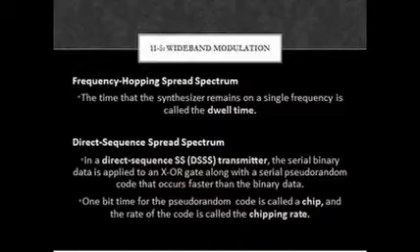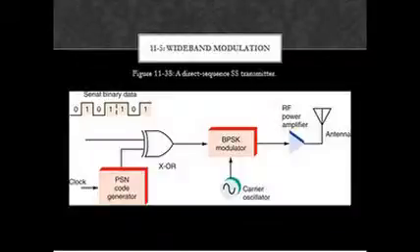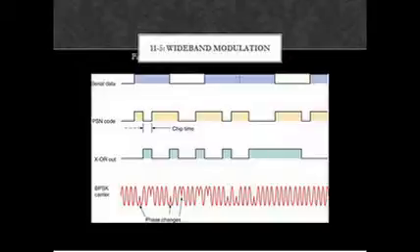Another wideband modulation method growing in popularity is called OFDM, also known as multi-carrier modulation. This relatively new form of modulation was first proposed in the 1950s, but was not seriously considered until the 1980s and early 1990s. Figure shows the concept of an OFDM modem. A single serial data stream is divided into multiple slower but parallel data paths, each of which modulates a separate subcarrier. A simplified version of the process is shown in the figure.